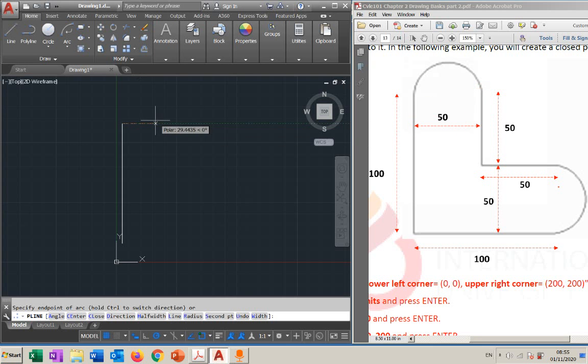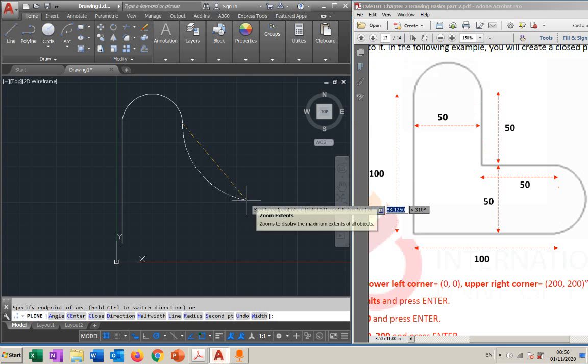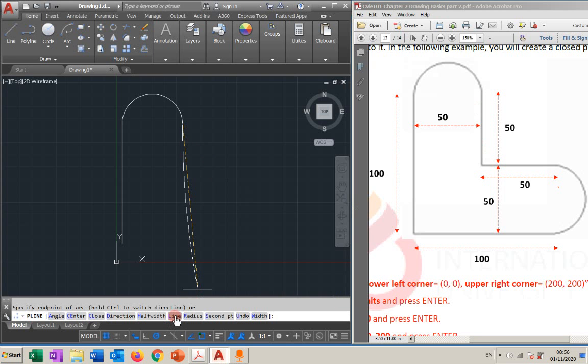Look at how easily I can go. I can just simply move like this, make it, this 50 is horizontal. I can make it like this horizontal and type 50, hit enter. It will draw it for me. It's arc. I'll change back to line, yes? I'll just simply type L, which is here for line. Look, I can click here or type L, stand for line.